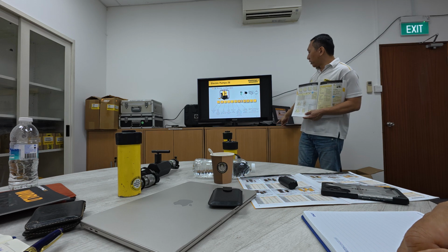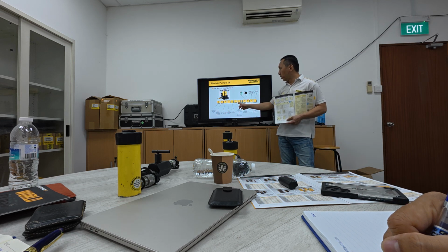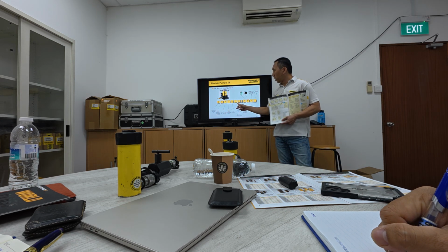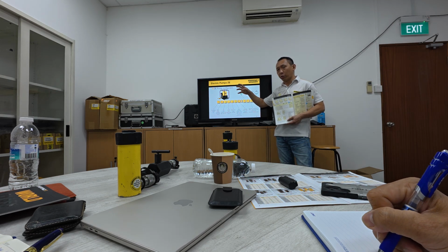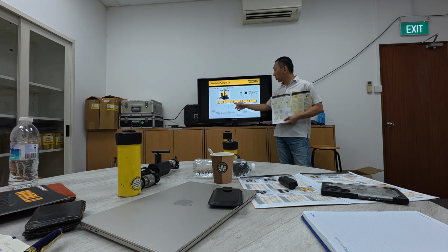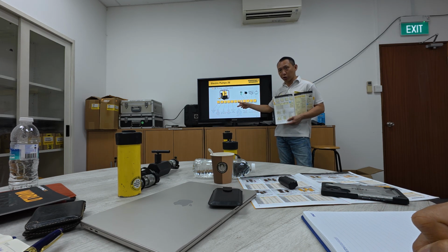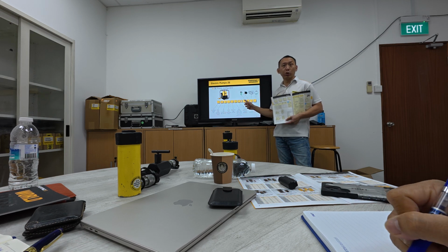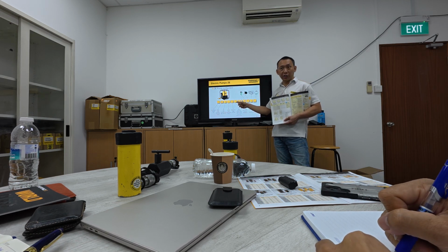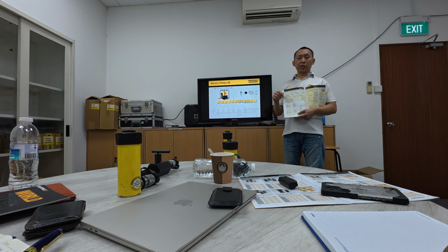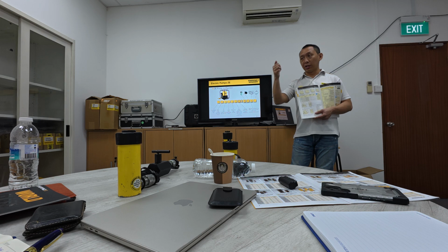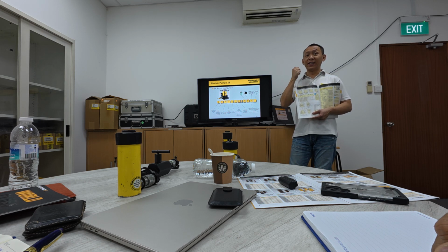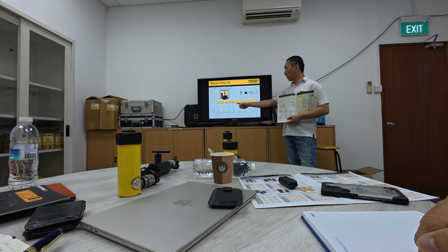Next up is the valve operation, which is linked together with the valve type, the 4-way 3-position or 3-way 3-position. This one will be whether it's a solenoid type or a manual valve. If the customer prefers manual, then we use M. Solenoid means the remote pendant control, the S. So this is the type.